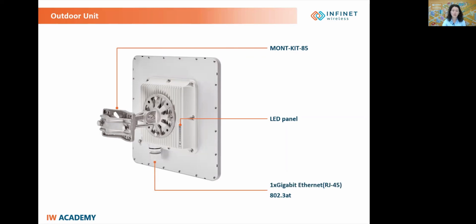The RJ45 socket is used for connecting to the power supply and to the network as well, via the power over Ethernet power supply. The network connection to the ODU is made using a 1 gigabit Ethernet connection, and the power is provided to the ODU, or to the Quanta 5 unit, over the Ethernet using a standard IEEE 802.3af passive power over Ethernet power supply.